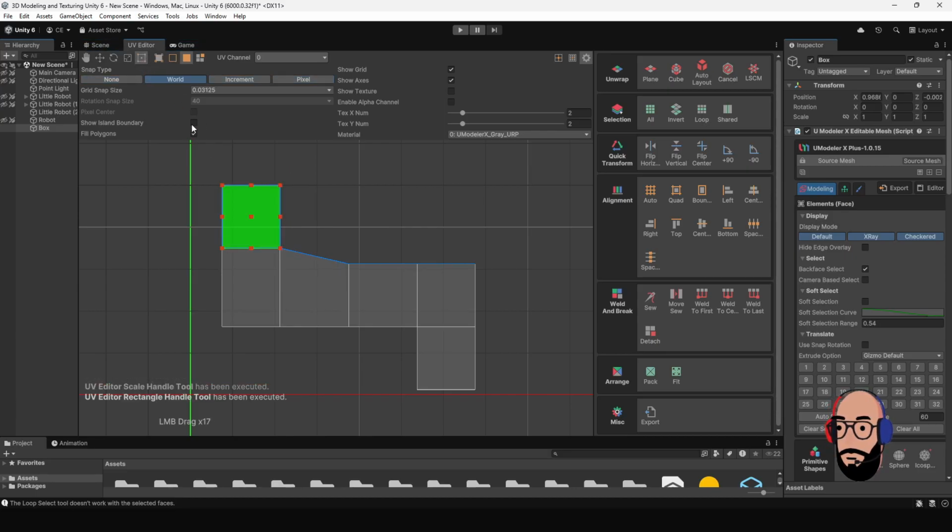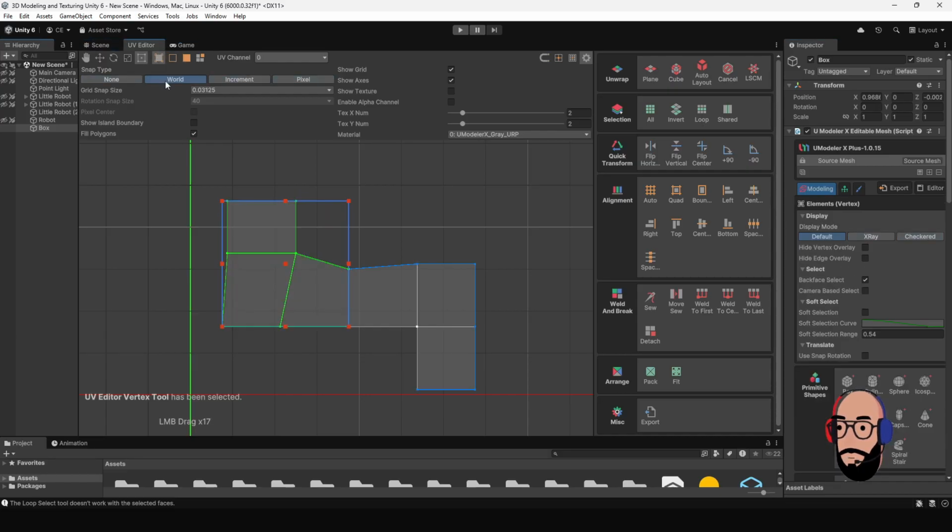You have this rectangle tool. It allows you to move it, but it also allows you to grab it and move based on different points that you have. Anything that you select, you can move like so. Very useful. Next to that, we have our vertex tool. Because we're still in the rectangle tool, I'm going to go back to move, and now I have the option to select this vertex like so. This is how you would manipulate your verts as needed.